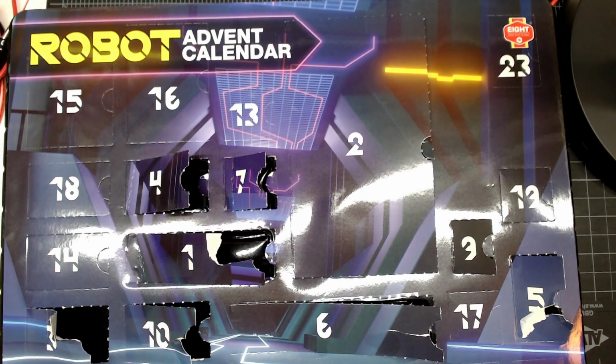Okay, I've been on this H-bridge kick for a while. We are on day 11, and we've gotten two transistors. And the reason why I kept saying things like, well, I think there's going to be a transistor behind this door, is because an H-bridge requires four transistors and often several diodes, depending on the type of transistor. A lot of times a MOSFET is used, and it may already have a diode internally. But a bipolar H-bridge is like four transistors, four diodes, a pile of resistors. I mean, it's not a super trivial circuit.